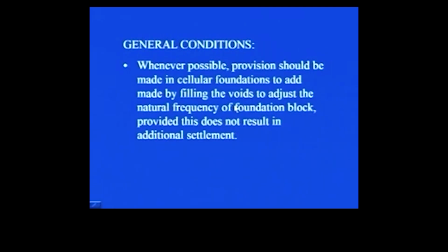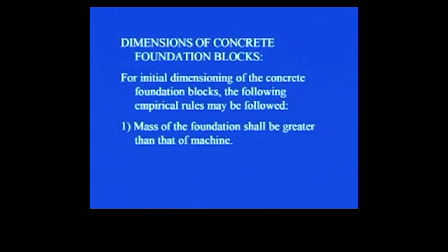However, when you put the extra load or extra filling, or you fill that particular void which is there in the cellular foundation, that should not cause additional settlement, because in any case the settlement should not cross its permissible limit. So, in case the settlement is within the permissible limit, this option can be used as far as cellular foundations are concerned. Then, how we can decide upon the dimensions of concrete foundation blocks.